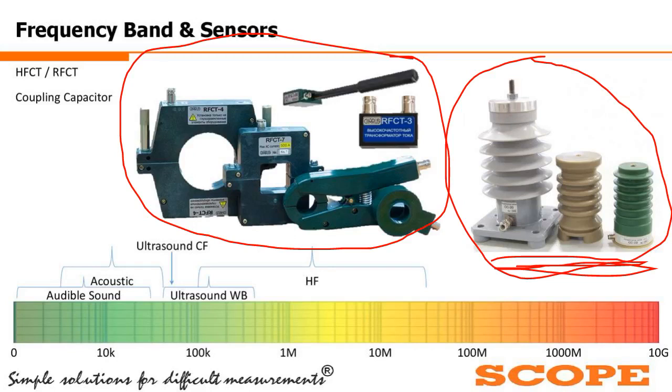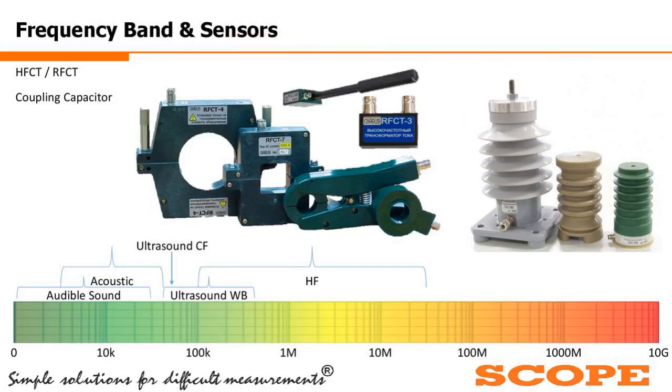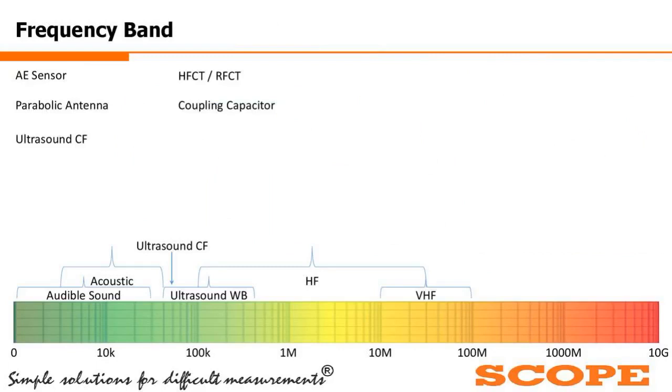Either they will fool us, because these are special types of capacitors, not available readily in the market. We require a lot of design, because we have to take care that inside these coupling capacitors there should not be any PD. So people are not generally ready to change the specification. So we should be concerned about the voltage level more, not the value of the capacitance.